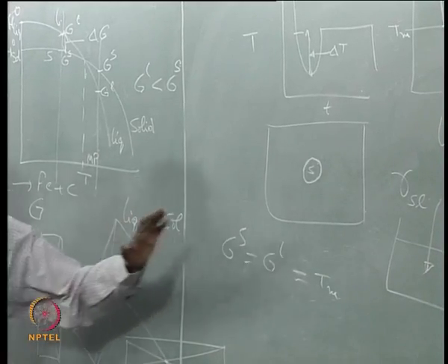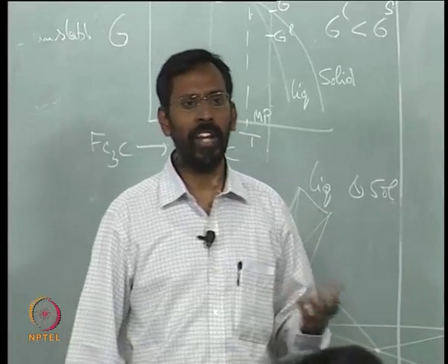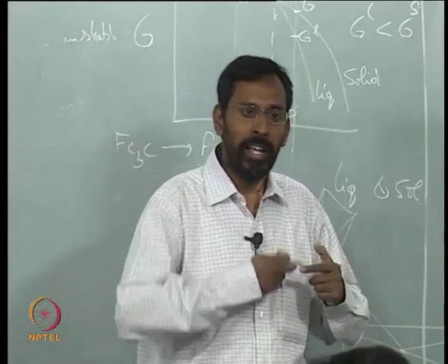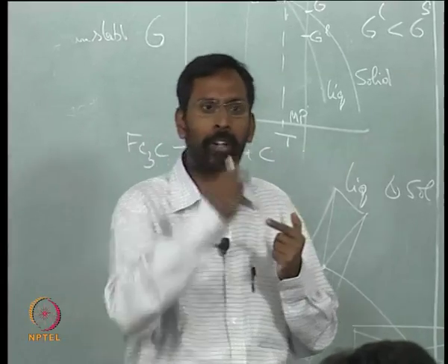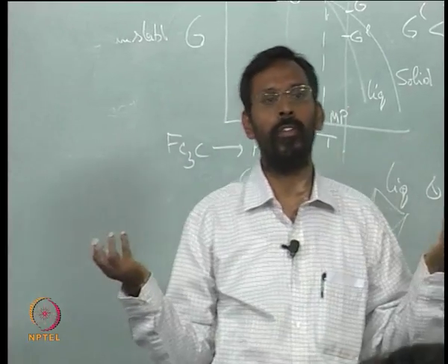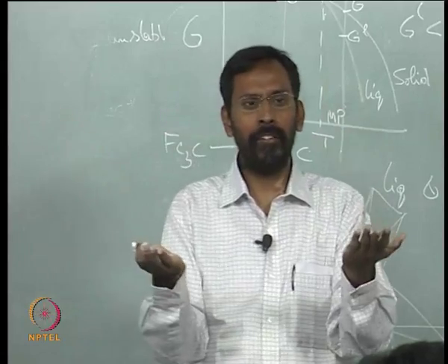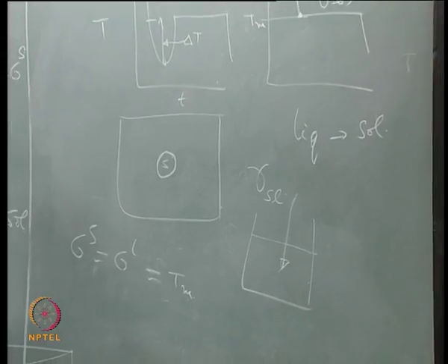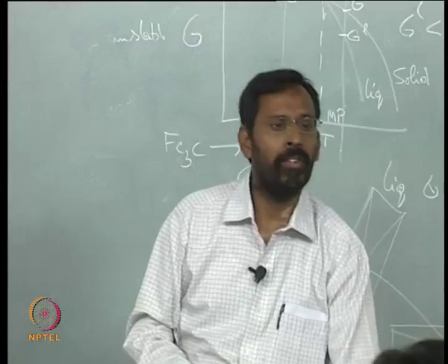So we say this is the melting point where the free energy of both the phases is equal, and if the free energy of both the phases is equal, for any transformation either from liquid to solid or solid to liquid, there is no driving force. If I take a liquid, keep it at the melting point, in principle it will not become a solid.